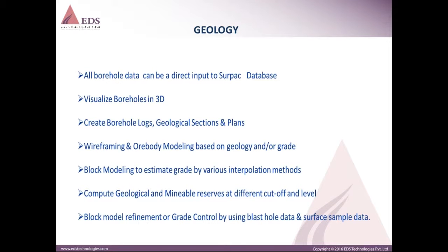And coming to geology, the application of Surpac software, especially in geology, is to create your borehole database from the exploration data. Once the borehole database has been created, you can visualize those boreholes in a 3D graphics window. You can create borehole logs from the database and create geological plans and sections. Once the geological sections have been created, you have determined how your ore body is behaving. So you can wireframe those and create an ore body model based on the geology or based on your grade. You can wireframe your ore body based on both lithology or grade also.